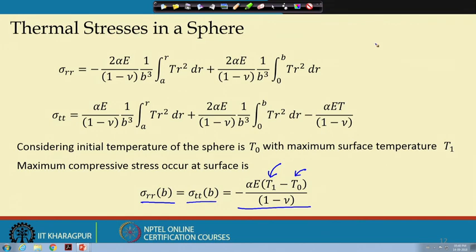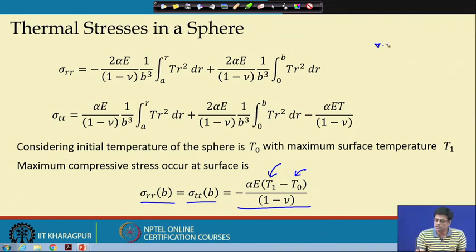So if you remember Navier's equation of elasticity, which is divergence of stress plus B or F equals 0, if this contains a thermoelastic deformation, which is in terms of alpha delta T for an isotropic material, this essentially goes to this side.